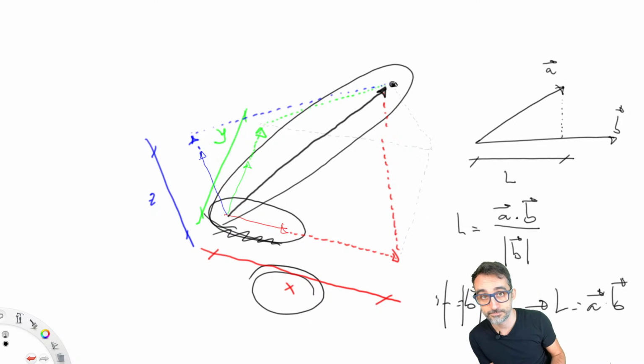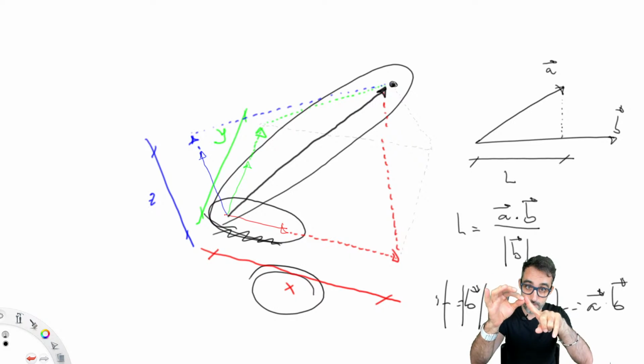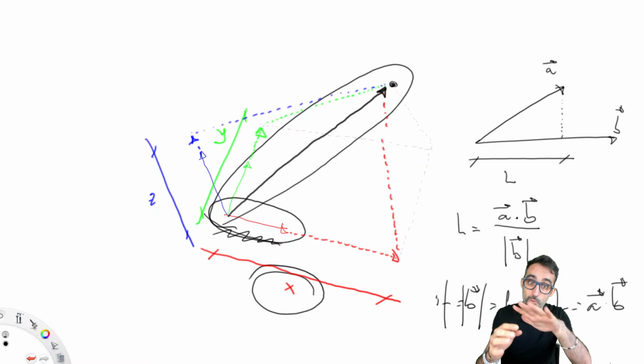All right. So that's going to be very simple. What we're going to do in this gem is create a local frame. We're going to create a position vector from that frame to that point. We're going to project that vector on top of the 3 axes, and that's how we're going to find the 3 coordinates of that point in regards to that local coordinate system.